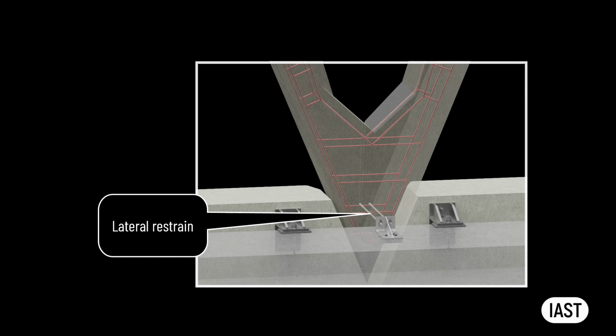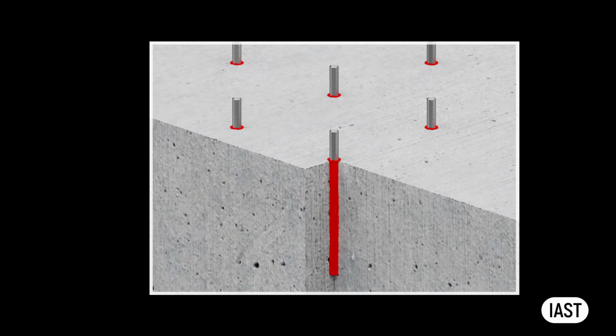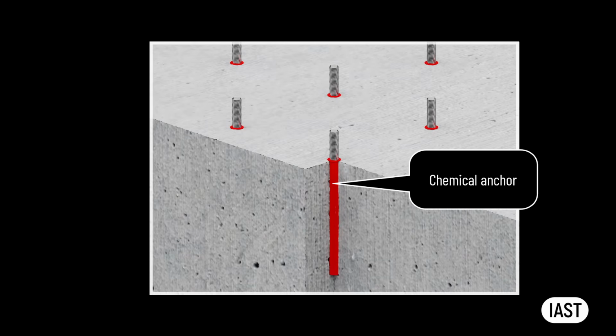The most challenging condition for selecting suitable fixings into the concrete is most likely to be a lateral restraint at the bottom of the panels. It is a sharp, narrow corner. Rebar connections are concentrated in this area, and the distances to the edges of the panel on either side are fairly close. Adhesive anchors, commonly referred to as chemical anchors, could be considered for this and similar applications.